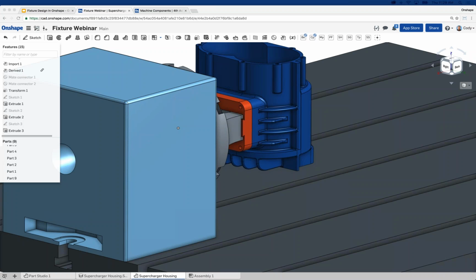Can I select all tangent edges once? If you grab the face, it will do that, yes. If I try to import a subassembly file, DWG, and manage to import it, but when I try to use it as a subassembly reference, it did not work. It's important to keep in mind, if you're importing a DWG or DXF, those are 2D CAD files. You could then take your DXF or DWG and extrude, revolve, sweep, or loft it and create a 3D model. But you're not going to be able to reference it as a subassembly. Forgive me if I'm misunderstanding there.